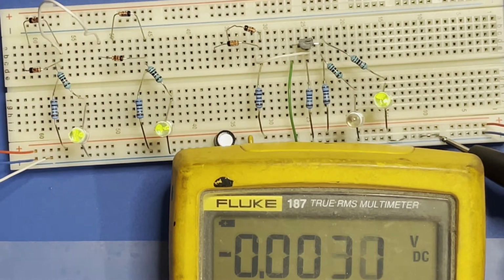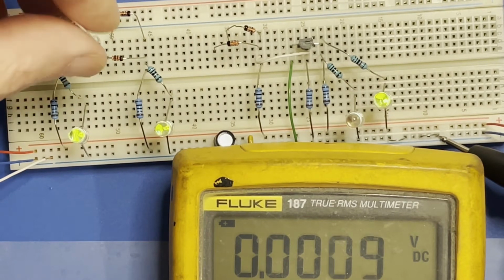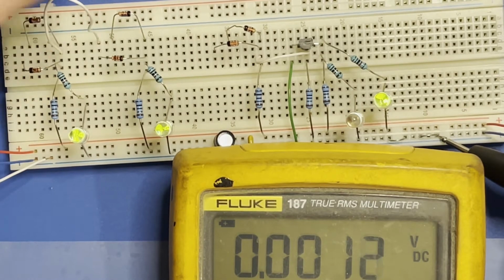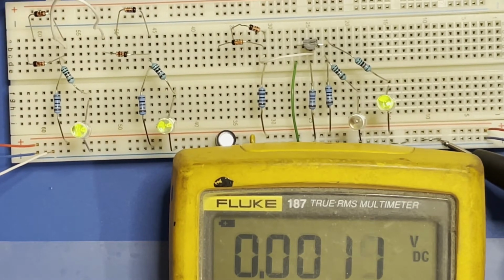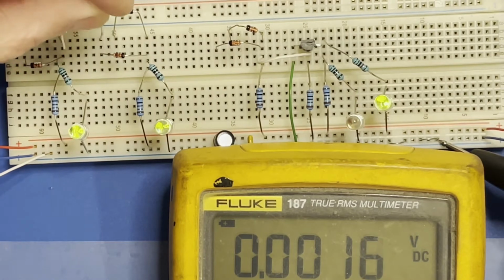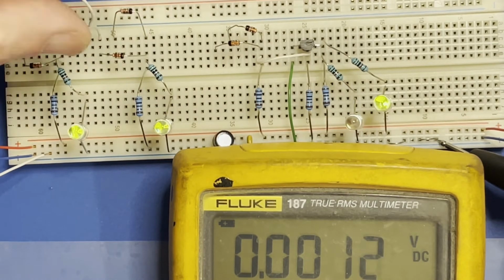They're not practical for real-world applications a lot of the time. Sometimes diode logic can be used for some things. It can be used as a single stage, at least, for combining different IC outputs, inputs, and when you're playing with logic circuits. And it can occasionally be useful. Or converting a switching output that actively pulls high and low to an open collector output equivalent by using a diode so it can only pull low, or vice versa, so it can only pull high. So there are applications, but only in isolated cases.